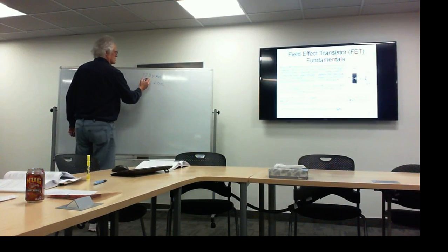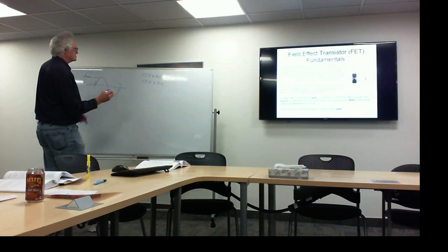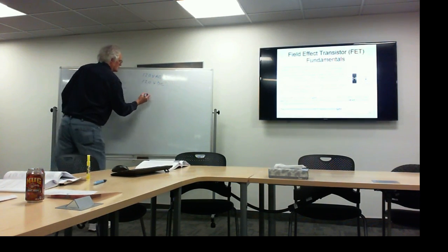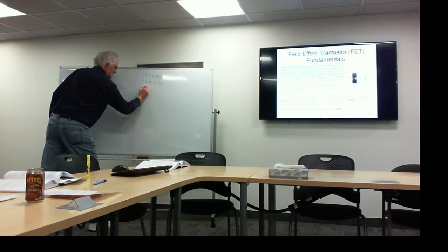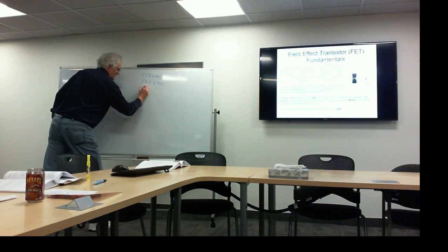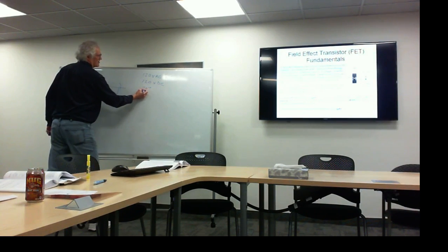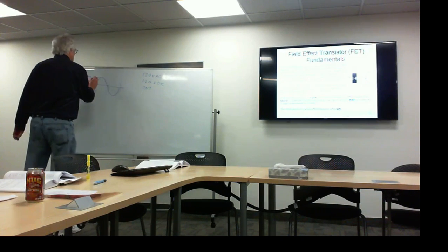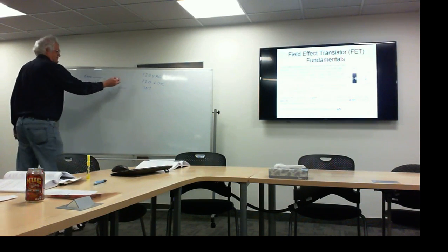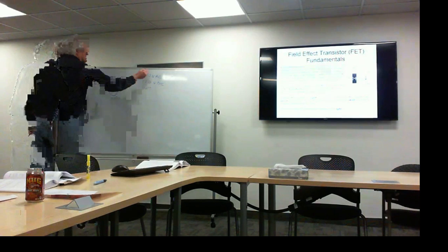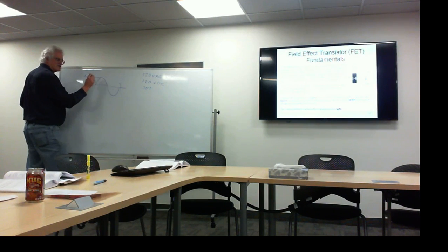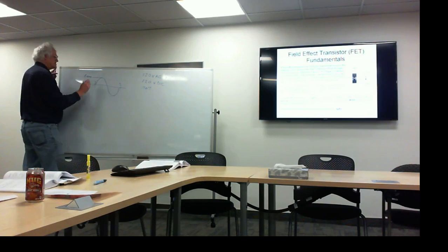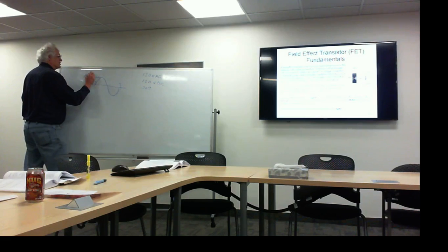So, in this case, for a 60 cycle sine wave, the RMS value works out to be, you don't need to know this, but 70.7% or 0.707 of the value of this peak. So this peak value here, if we measure that on the scale in time, would actually be 169 volts.